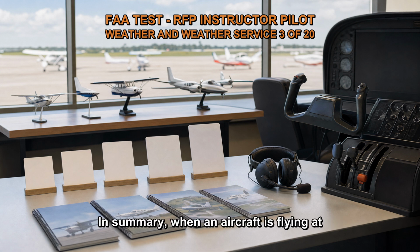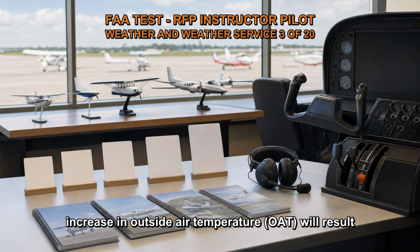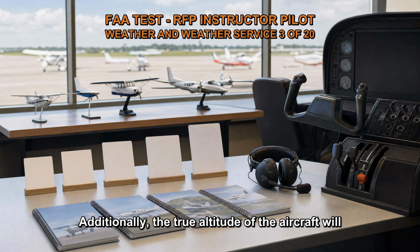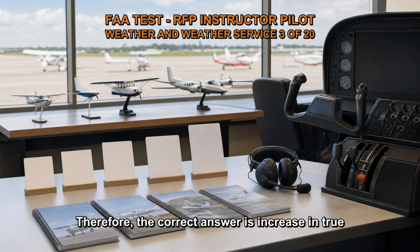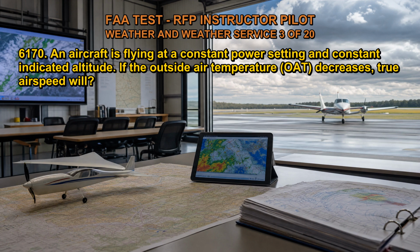In summary, when an aircraft is flying at a constant power setting and indicated altitude, an increase in outside air temperature, OAT, will result in an increase in true airspeed. This occurs due to the decrease in air density associated with higher temperatures. Additionally, the true altitude of the aircraft will increase as the indicated altitude may slightly overestimate the actual height above sea level. Therefore, the correct answer is increase in true airspeed and true altitude.